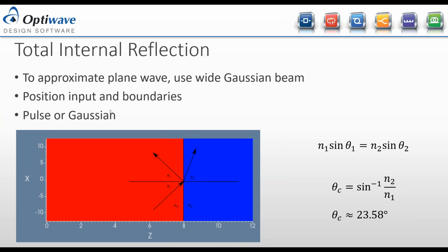But I don't think it really matters because it's not like a frequency-dependent simulation because our refractive indices are constant, and there's no dependence on wavelength here. But they'll give you different results. One will finalize itself once the simulation has reached equilibrium, whereas with the Gaussian pulse, you have to set the time step manually. So I don't think it really matters. Maybe there'll be subtle differences in behavior, but I don't think it'll be a big important part of it.